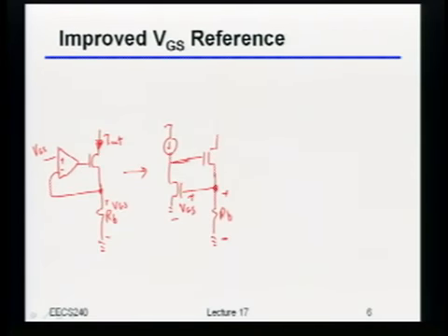But I still cheated. So what's the cheat that I used right here? Bias current. Yeah, I still have a bias current flowing in that amplifier, right? Where is that bias current going to come from? Well, how am I going to cheat one more time, but just in a clever way? Use a mirror. Yeah, I'm just going to take the thing that is my bias current and feed it back into my amplifier, right? So in other words, just to be clear, this is what we had so far.